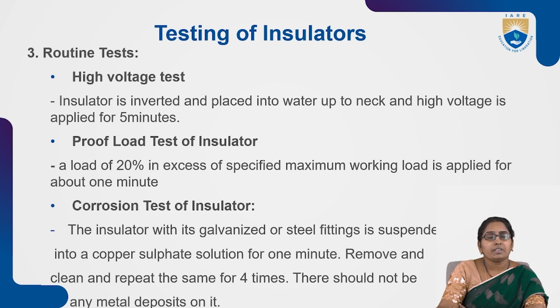The insulator is inverted and placed in water up to the neck, and a high voltage is applied for 5 minutes. It has to withstand that. So that is how a good insulator should be.